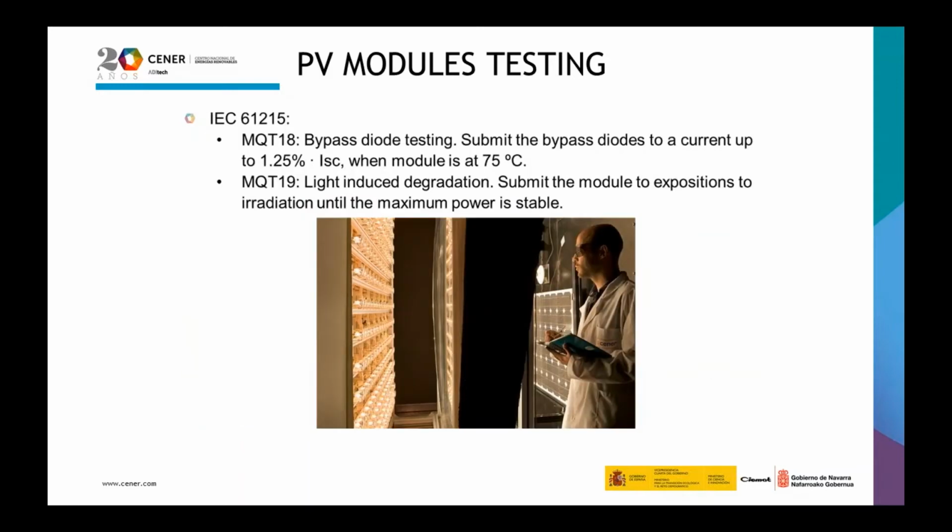Finally, we have the MQT-18 bypass diode testing, where the bypass diodes of the modules are assessed to check that the thermal design is okay for the final application, and to check that the module is properly protected with the bypass diodes from the hot spot effects.